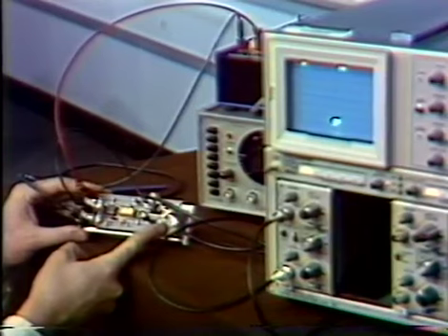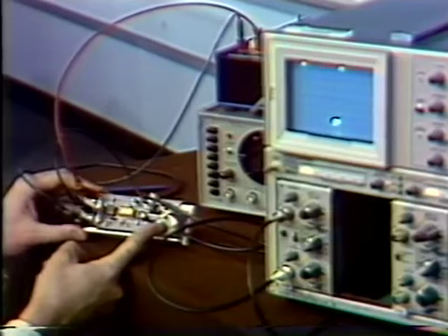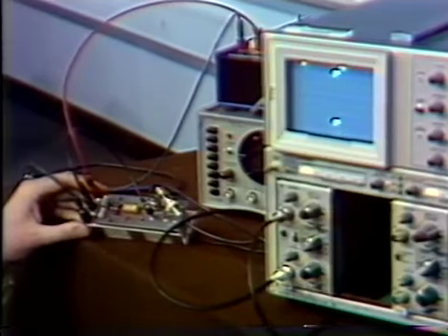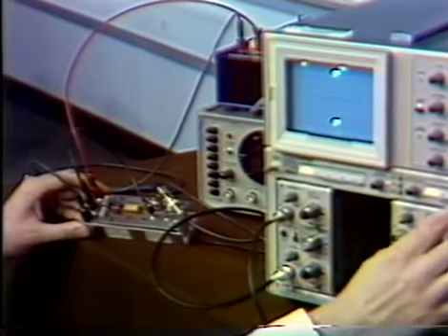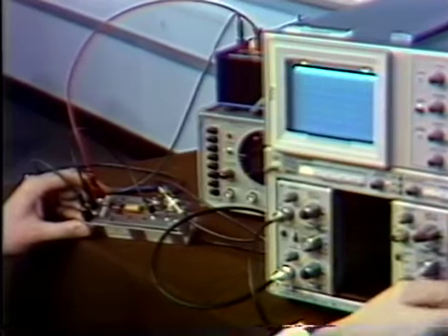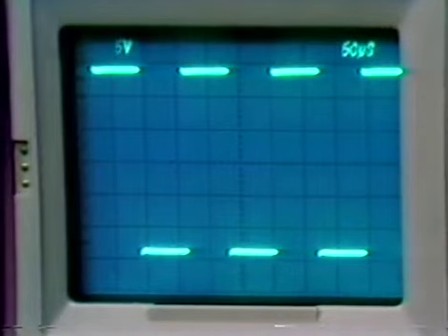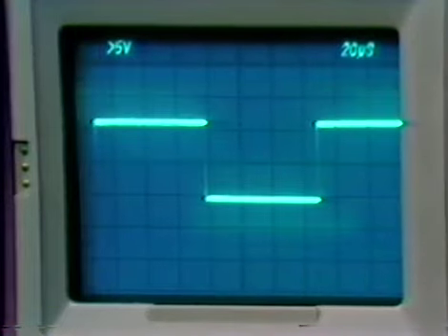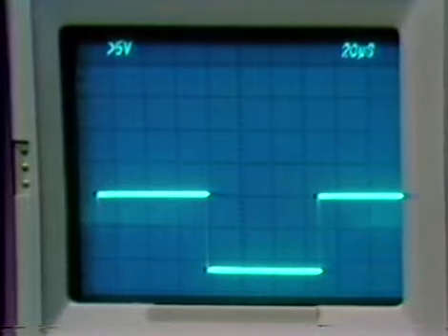With the switch in the position shown, it disables the loop so that we're able to easily plot the Schmitt trigger characteristics. When we close the loop, the circuit oscillates, and we can look at it on a time base. And here now is the square wave coming out of our function generator. Let's look at it on that time scale possibly, and let me lower the amplitude of that a little bit so that we can duplicate the picture that we had earlier in the view graph.